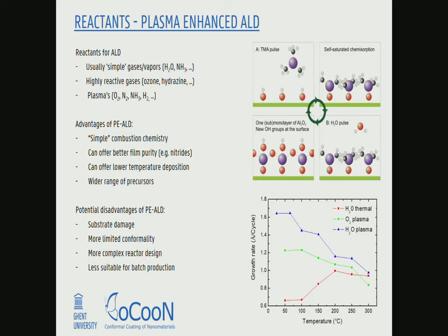Of course, there are also some disadvantages. You can have substrate damage if you're not careful. Typically, the conformality is a bit more limited. Your reactor design becomes a bit more complicated, and it's also maybe a bit more difficult to scale to batch scale. Anyway, if you're interested, you can read more about this in several excellent review papers on plasma-enhanced ALD.